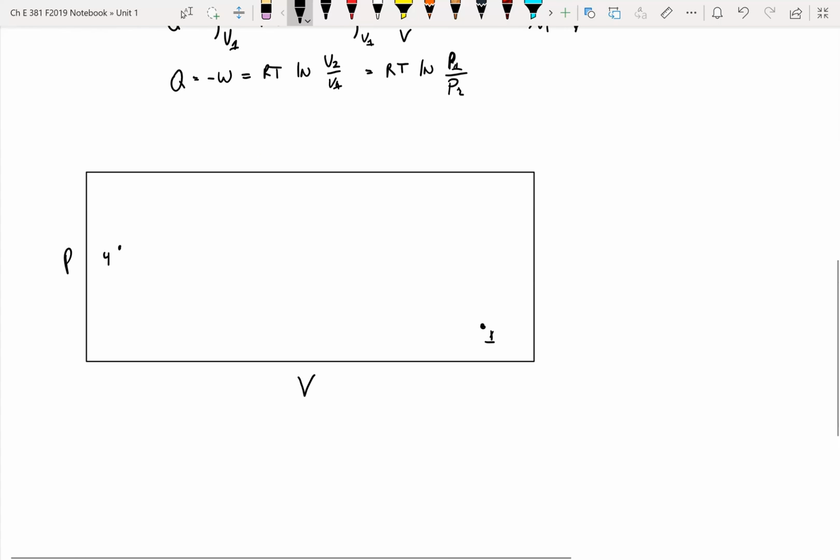So the rate at which you do something matters in which process it mimics, and that changes depending on those sorts of things. But at any rate, if we compress the cylinder really quickly, too quickly for any heat to escape, then it's going to be another curve. It's usually not going to be a great equation to describe the path of that curve. We'll get to an exception to that. So if I don't do anything to release the heat, then I'm going to end up injecting all that mechanical energy and converting it all into stored thermal energy by raising the temperature.